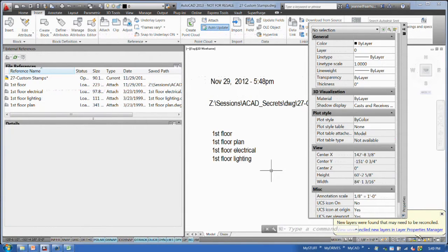And then the pick box, if you're having trouble with it, there's a new variable in the newer releases of AutoCAD that controls how you pick things. So review the pick drag variable, and it's in the handout, and see if you need to tweak that, because they've been playing with how that works in the last couple of releases. Also, annotation background, if you place a piece of text.